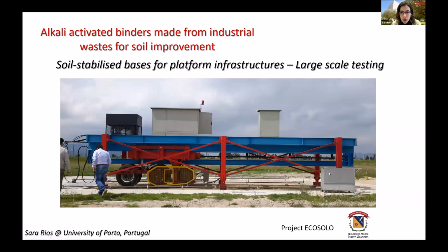Also, with this project with the Universidad Militar Nueva Granada in Bogotá, Colombia, we've tested this material in a subbase, tested with this wheel test. So it's basically a wheel that goes back and forward over the layer that we are studying, and we can measure the deformations and the weathering that this layer suffers due to the cyclic loading imposed by the traffic.